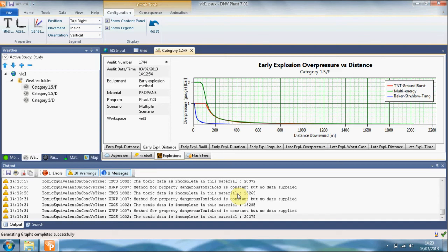They're raised 0.5 meters above the ground and are delivered with a fill level of 80%. The propane is under the same condition as in the sphere, under saturated conditions at atmospheric temperature. There are many hazardous events that could be modelled for the tank wagon, including leaks during the unloading process. This tutorial will consider only the rupture of a wagon under normal operating conditions, a leak from the liquid side of the wagon, and a fireball produced by catastrophic rupture of a wagon under flame impingement.